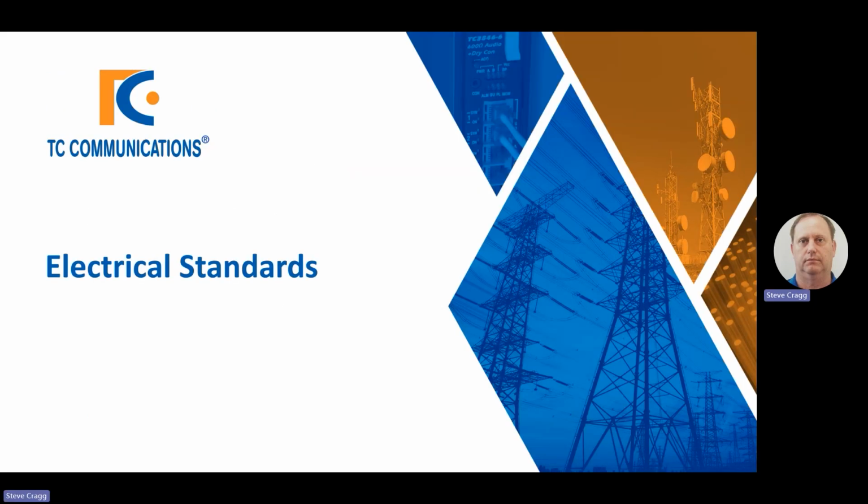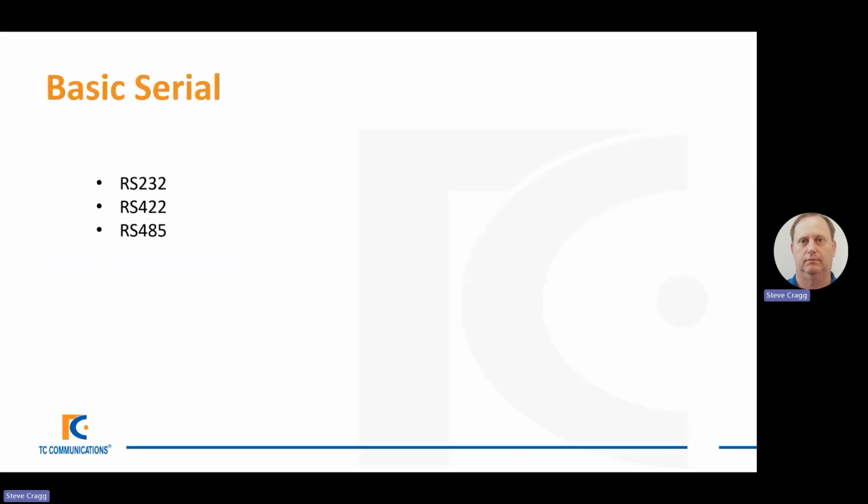Let's look at electrical standards. In the serial world, I think most people who have dealt with serial will have come across some or all of these terms. RS-232 probably being the most common and the original of these standards, RS-422 and RS-485. It's very important to note that these are electrical standards. So when somebody is explaining that they are using RS-232, it is quite possible to be compatible with RS-232 in the fact that two devices have the same voltages.